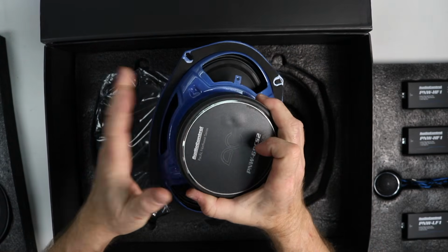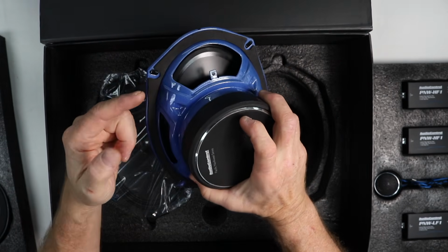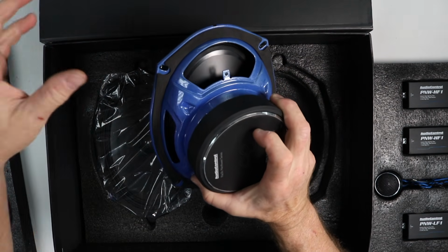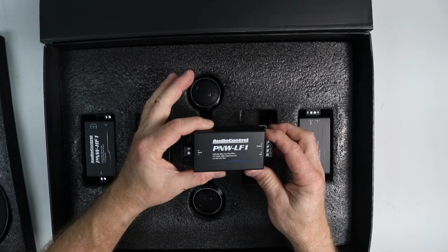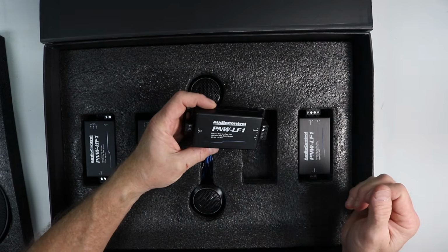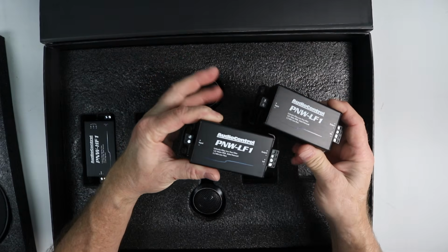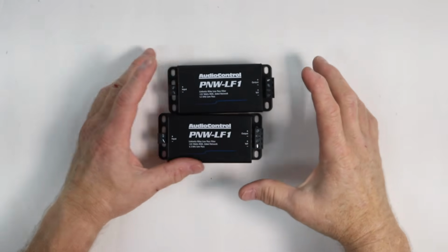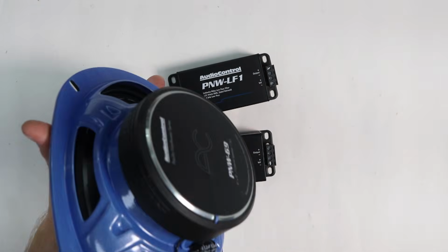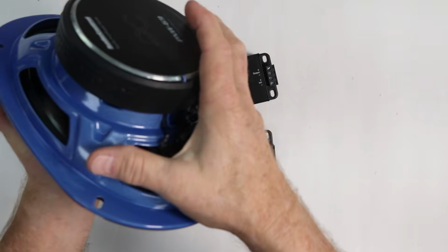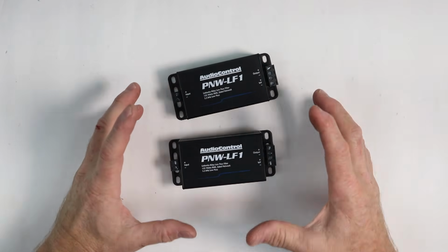A lot of the times the mid-bass was not located in the same place as the tweeter. They both weren't in the door. Therefore, you couldn't just put a cap on here and run some wires up to the tweeter. It became a little bit more complicated than that. And that takes us to passive crossovers that were separate from the speaker. On this particular set, we have a high pass and we have a low pass. Because we are going to make a dedicated external passive crossover, we had a little bit more real estate. We didn't have to worry about tucking it up into the basket of the driver or behind the speaker or something like that. So we could build better passive crossovers.